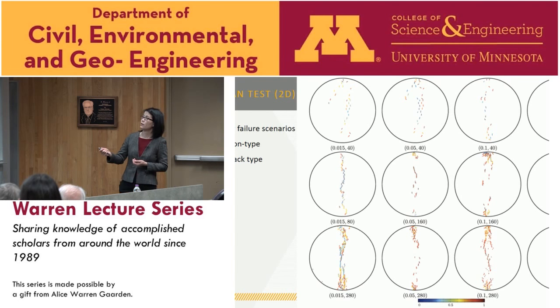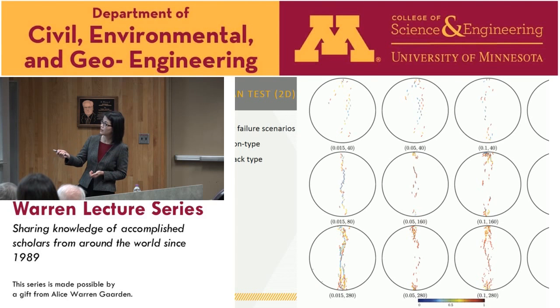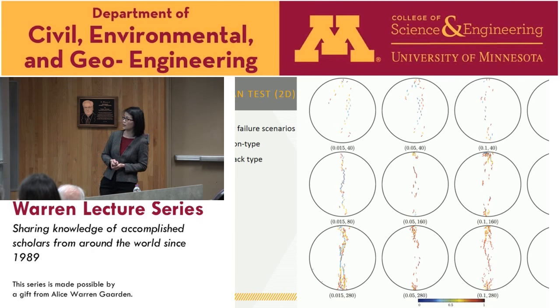But the interpretation of the Brazilian test really assumes that you have a center crack. A crack develops in the center and goes both ways, because the elastic solution tells you that in the center there is nearly uniform tensile stress, although it's confined.